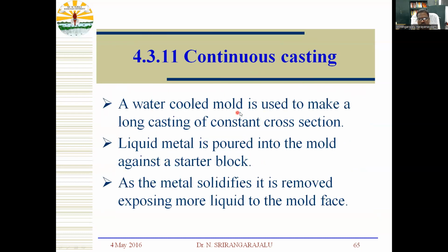A water-cooled mold is used to make a long casting of constant cross-section. Liquid metal is poured into the mold against a starter block. As the metal solidifies, it is removed, exposing more liquid to the mold face. This is a continuous casting process.